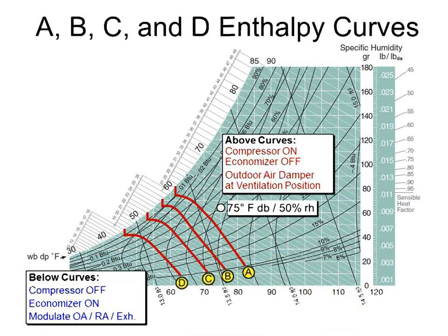We look at those ABCD curves on the economizer controllers. Those represent the enthalpy settings, and these are what those curves look like. There's a little hard shut-off at the high humidity point, but then after that, it's actually a curve, right? When I do these classes face-to-face, I always ask everybody, what curve do you think technicians set it for? Almost all the time in the field, I see this set on D, which is a super conservative number that they know they'll never get a single callback on no matter what.